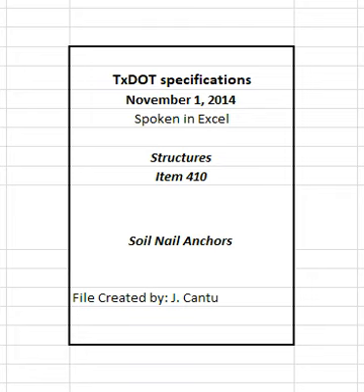Install additional soil nail test anchors following the modified construction procedures and test additional soil nail test anchors if the contractor chooses to modify construction procedures after test soil nail anchors are completed and approved. This additional testing is subsidiary to this item.